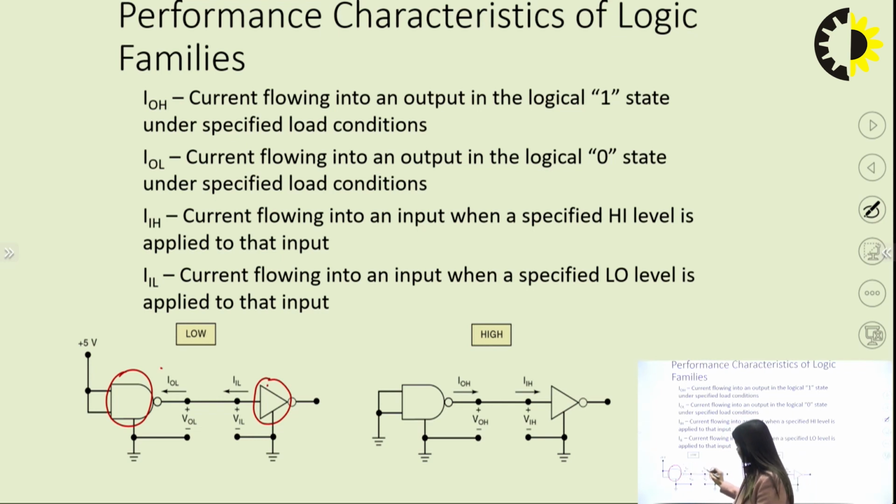The propagated bit between the two gates is 0 in this particular case. Here it is the positive voltage and this positive voltage will go here, right, and this VOL should have that minimum value so that the other can recognize it, that is IIL. So if this current is going like this, another current will also go like this, see IOL and IIL, right.